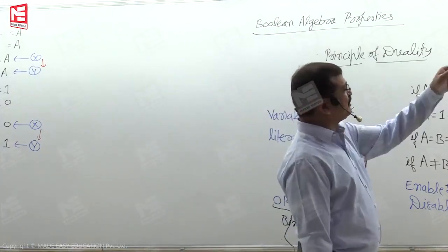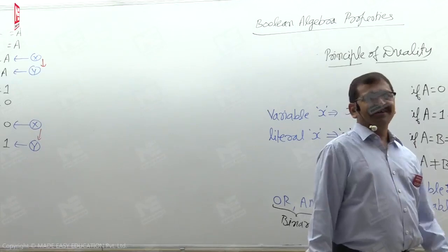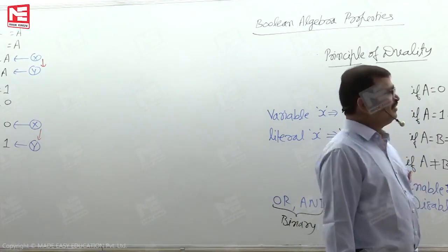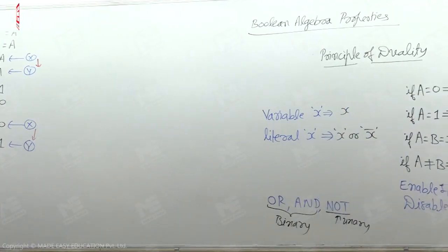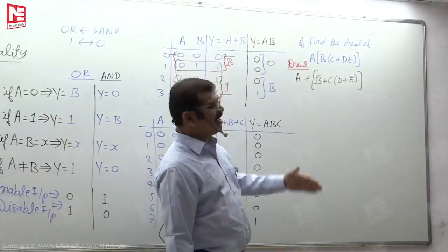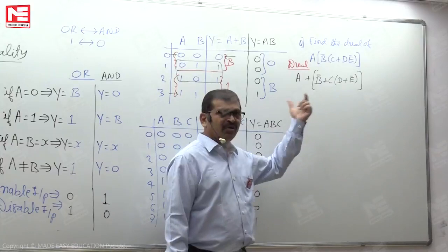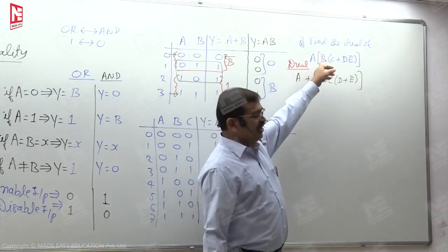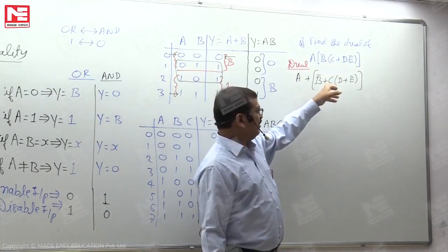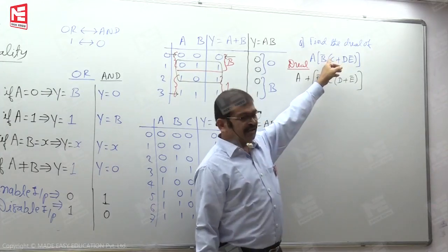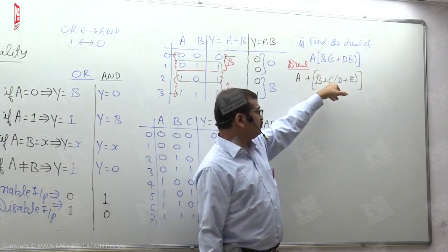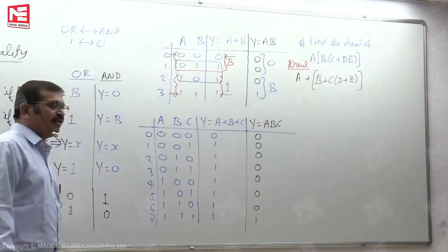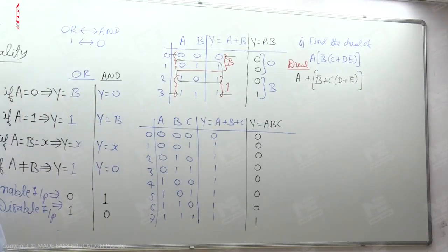Using this terminology, we can talk about the dual operation. In the dual operation, the literals are not affected. This is an observation from the example on the board, or what you tried yourself. The B variable was complemented, and after the dual operation it comes with the same complement. The C variable was without complement in the given expression, and after the dual operation C is still without complement, and so on. Hence, we have a conclusion: in the dual operation, there is no effect on the literal.